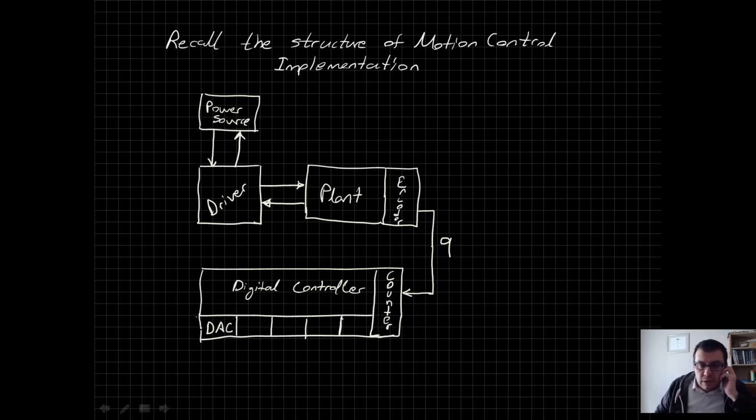So this digital to analog converter is responsible to convert the digital signals created inside your algorithm to analog output value, and it's between plus and minus 10 volts. That's a common industry standard. There are different DAC implementations where you'll find, for example, plus minus 5 volts or different range. But usually the industry standard is plus minus 10 volts for the analog signal.